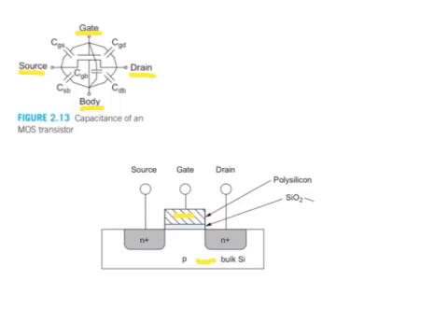In its most fundamental form, we can think about the capacitance as two pools of charges which are closely spaced together, whether they are separated by a dielectric or free space. And here, there does not need to be a metal plate. The free carriers in the gate side, free carriers in the polysilicon, or in older processes, free carriers in the metal, and the capacitance arises from the close proximity of the free carriers here, separated by the oxide here, and the free carriers in the bulk P semiconductor here.